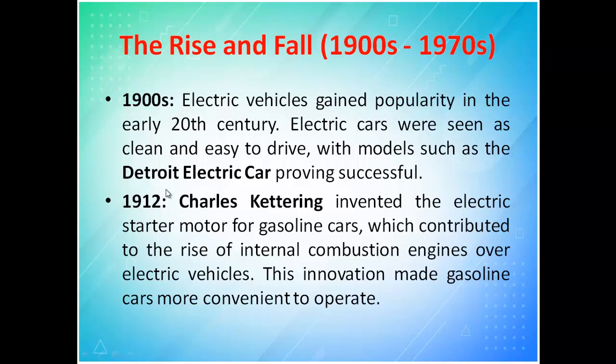You have diesel and petrol, but the thing is you cannot start the engine. You have to put a crank in front of the engine and try to rotate it. This is what we even now do in agricultural motors. You might have seen in a diesel engine there is a rod on the front side. You have to rotate it till the engine starts, and then the engine runs automatically. So manually you have to rotate and start.